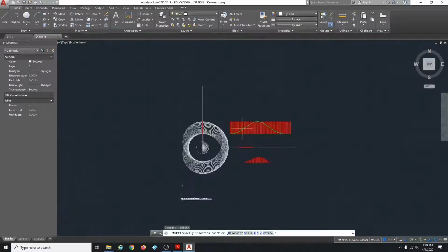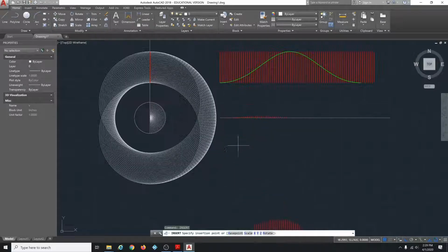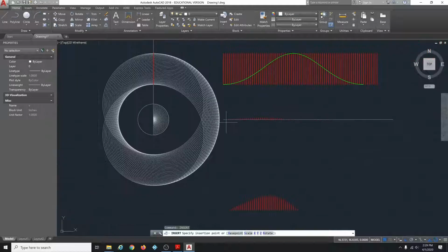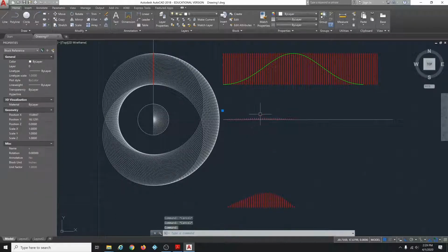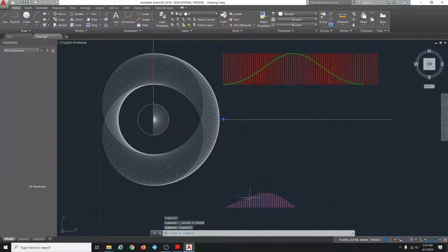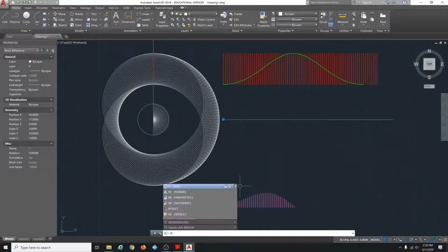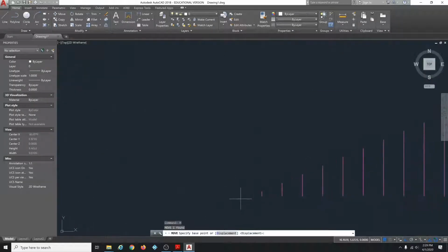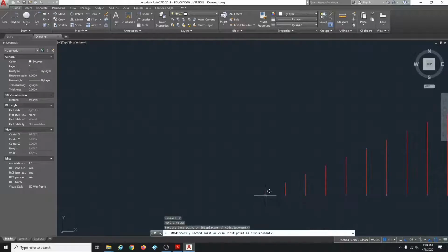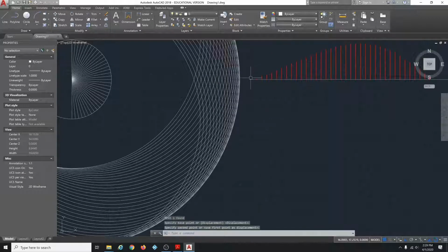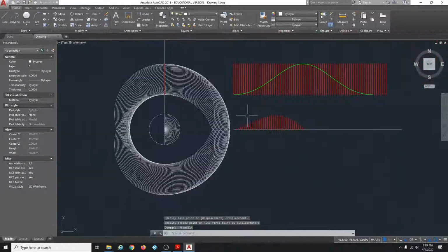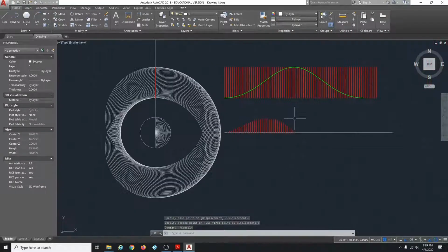Okay, yeah, it's way down there. Oh, shoot. I messed up my insertion point, but it's fine. I can still put it on the end point. All right. I'll delete this block that I made before, and I'll grab this thing and do a move command. We'll move it from the end point of that, move it perpendicular to that. All right, fixed.